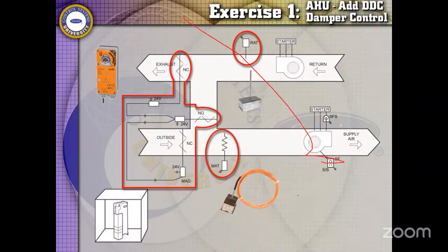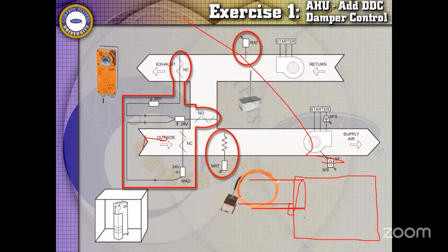There's my mouse. Okay. So let's say I'm looking into the airstream. I'm standing right here in this outside air duct, and I'm looking down that airstream right that way. And this is my cooling coil I see. I mount the mixed air sensor here, and then I serpentine it up and down the